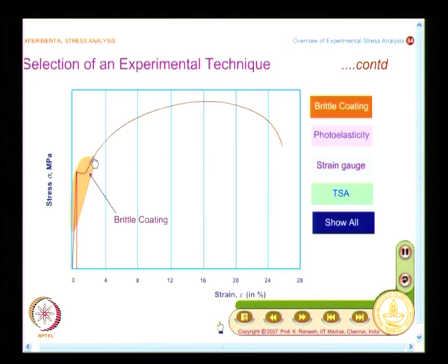What you need to worry about is the end point and the start point, roughly this range. And when I say photoelasticity, what does it indicate? I am essentially living in the elastic region. So, a photoelastic analysis will confine only to the elastic region, it will give you information. If I have to go for the plastic region, I have to go for photoplasticity.